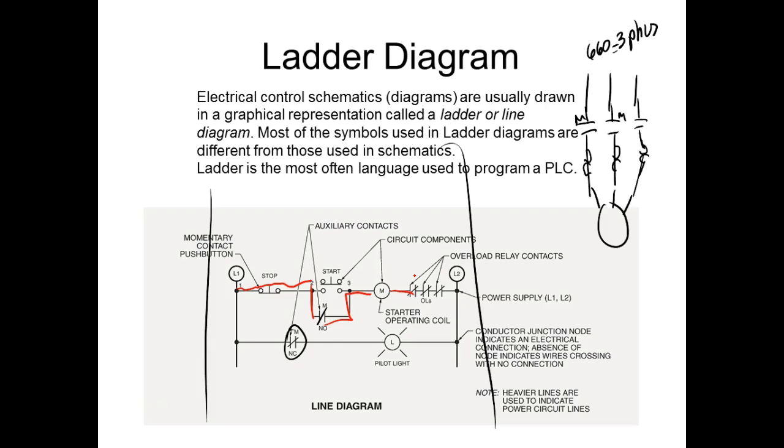And that's why we had 500-600 relays in that one house trying to do all that logic. Not trying to control the motors. We might have had one relay that controlled the motors. All those other relays were in there just to do the logic, just to do the automation part. And that's what PLCs replace. It replaces all those relays that did nothing but do what? Automate the system. So we can program this thing and then wire our motor starter outside of the actual PLC. So this is the symbol for the overload right here. If one of the overloads trips, it's going to open up, drop out, and the motor will drop out.